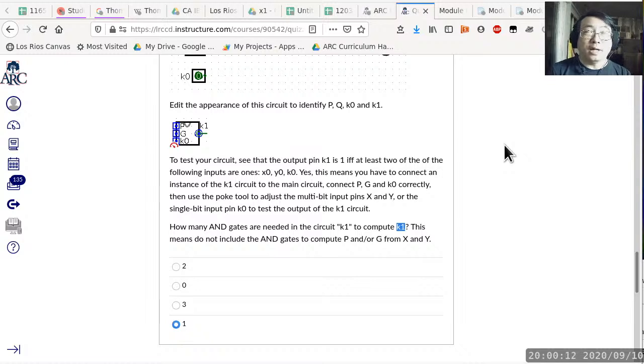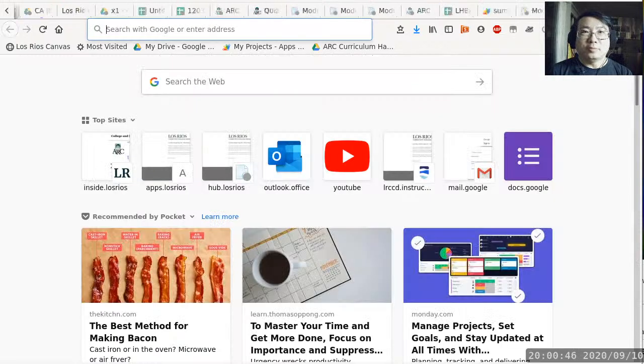Because K64 has 63 AND gates and one single OR gate at the very end. And then the connectivity, I mean, just imagine the splitters. Every input, every P, every G splits into 64 bits, and then the 64 bits fly everywhere within the subcircuit. It's not like you cannot do it. It's just not feasible. It's not something that you want to do by hand.